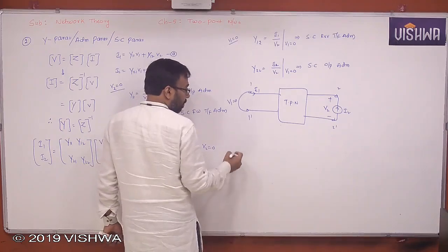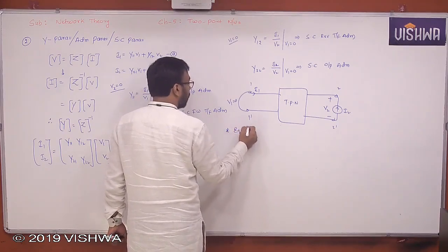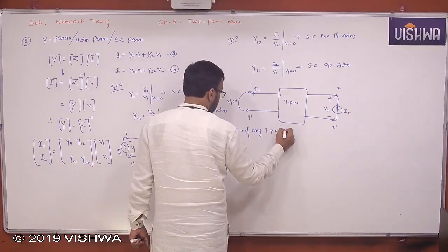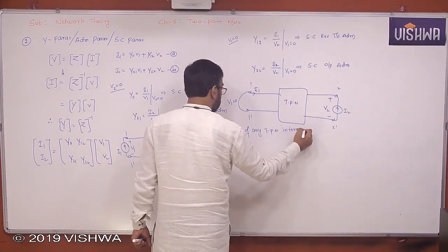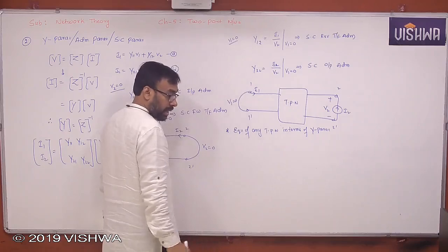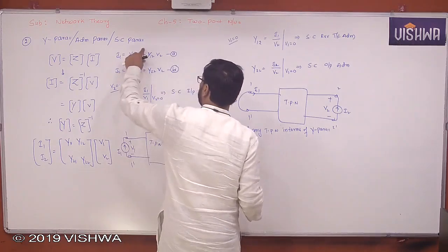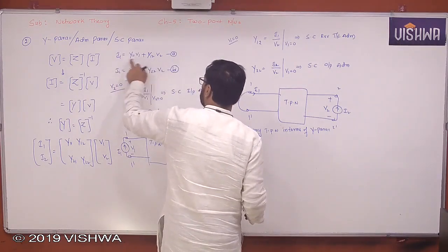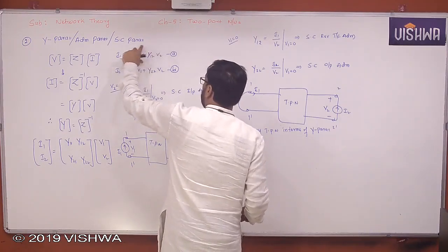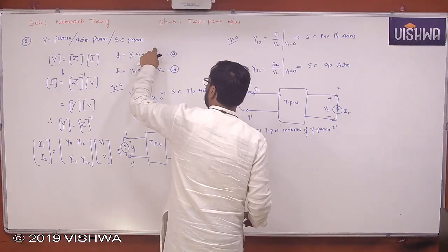Okay. Now I would like to construct the equivalent of any two-port network in terms of Y parameters. According to the first equation, I1 is equal to Y11 V1 plus Y12 V2. This is a current that should divide. This is one parallel branch, this is another parallel branch. If I connect these two parallel branches, the current flowing through them will give you the total current.